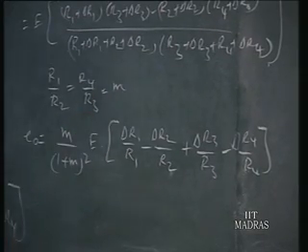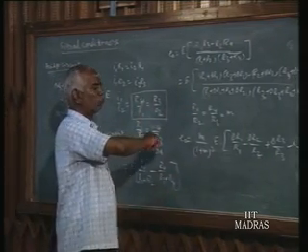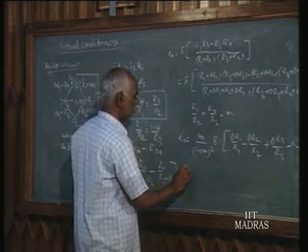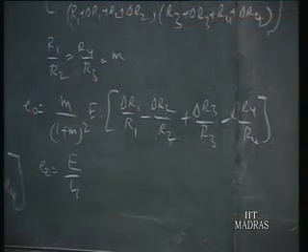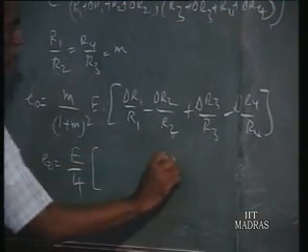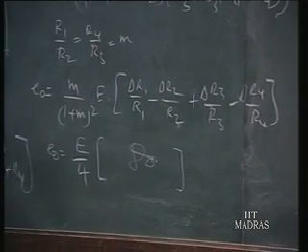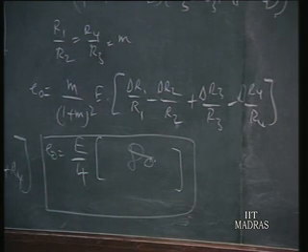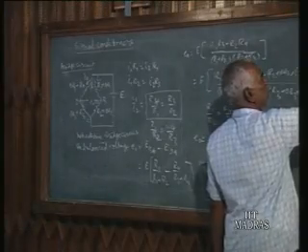Suppose M is equal to 1, that is the case in mechanical measurements. We are using strain gauges of 120 ohm each, an equal arm bridge. So M is equal to 1. In that case, you will find EO is equal to E by 4, since M is equal to 1 gives 1 by 2 square, that is E by 4, into the same term, whatever is inside the bracket. So this will be the imbalance voltage of a bridge. We will use this equation to find out the voltage output in different configurations of the bridge. First configuration is quarter bridge.